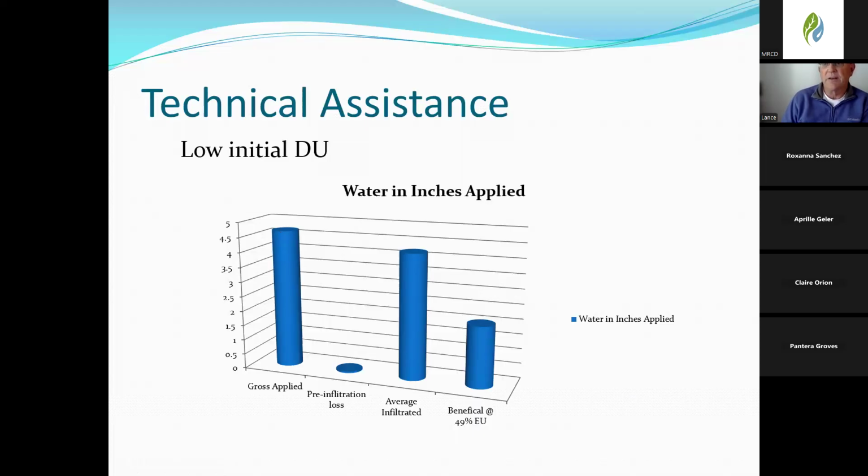Question, when you say 7.5 hours, is that in just one watering session or over a day, week, month? So that's saying that to meet that ETc what was required was 7.5 hours. The way that example was looking at it was more or less a single irrigation event, but it is possible that you could split that into 2 irrigation events, say a 3.5 and a 4-hour irrigation event during the week, whatever best works for your system, your availability of time, labor, those kinds of things.